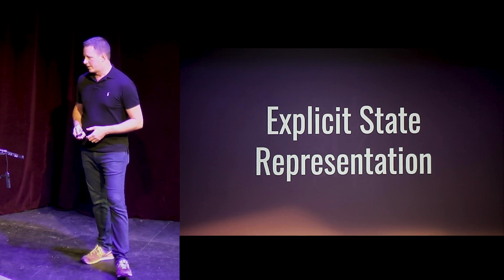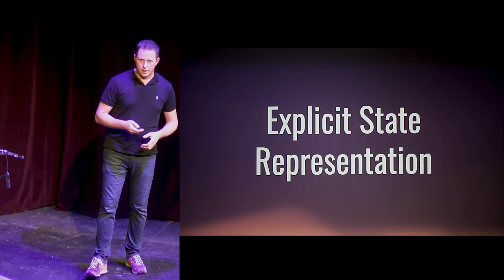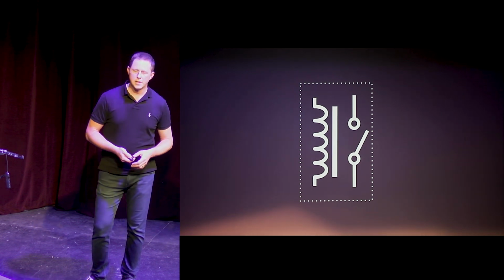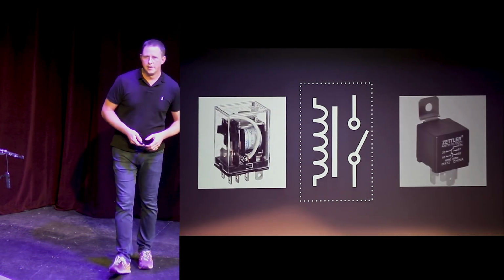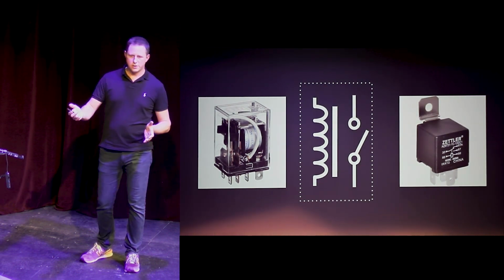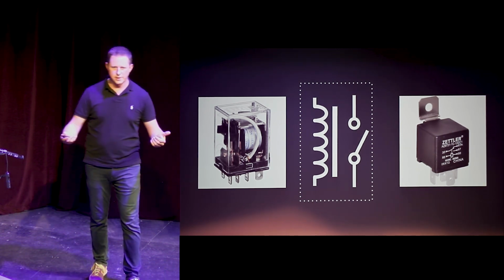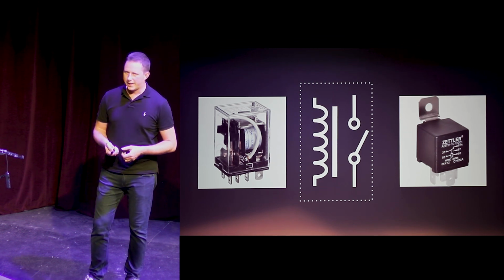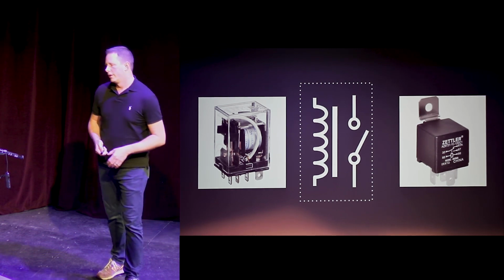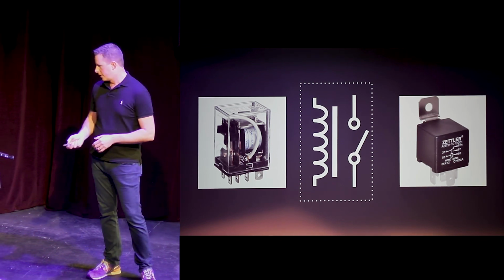So I can synchronize a software state with real-world state and make it really, really easy to see and work with. So as an example of that, as you saw, there's a relay board that's controlling all of these different valves. And a relay is simply a component that uses an electromagnet to change the state of a switch. So I can use one to isolate two different sets of power components. In my case, we have a Raspberry Pi that's low current, low DC current. I can charge the coil. And then on the other side is the 24-volt AC current that the sensors use.